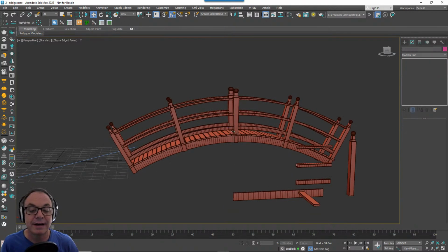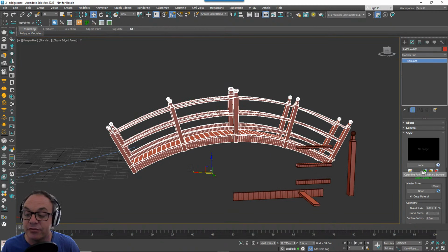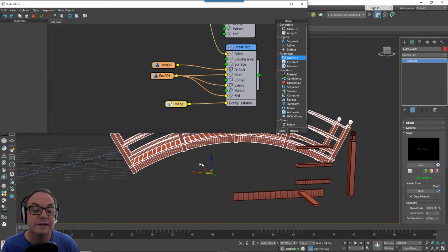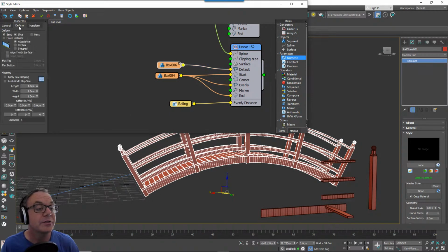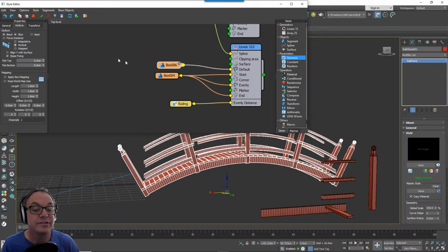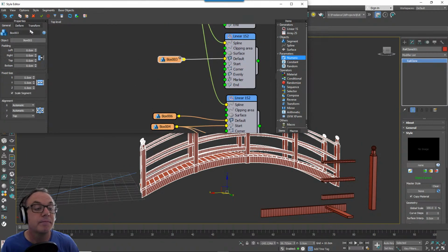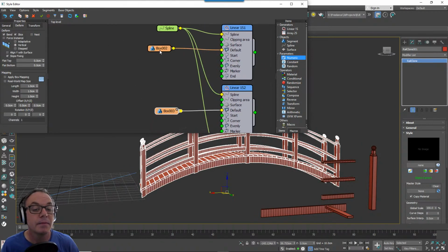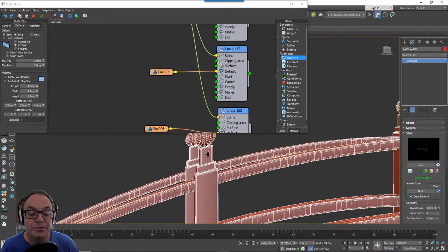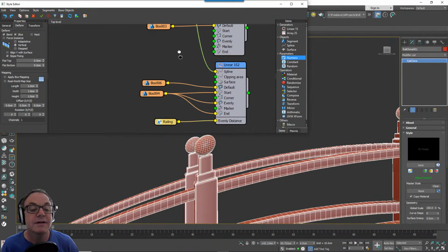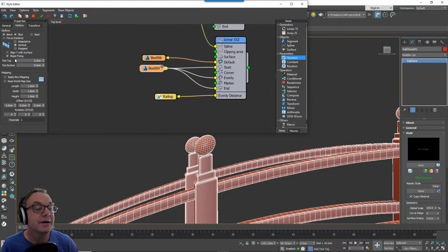So how would you fix that? You'd fix that by changing the deformation modes of those segments. So at the moment they're adaptive, which means they come out perpendicular like this. But what we can do is go into the deform tab for these segments and set them all to vertical. Like so. So now they're all vertical, and the only thing that's a little bit odd now is that the tops of these are a little bit strange looking. So we could fix that by changing flat top.